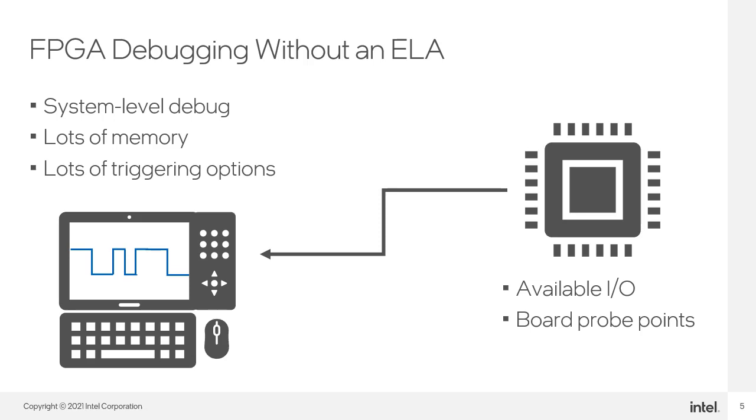Even if a signal is successfully brought out, there is always the possibility that a device probe or other board component could affect signal integrity or timing on critical signals. Even just the routing of such signals to a device I/O pin can affect the signal's behavior. While high-quality test probes can help prevent this, they can be very expensive. Once all these issues are taken care of, you can finally configure and use the test equipment to capture the tapped signals.